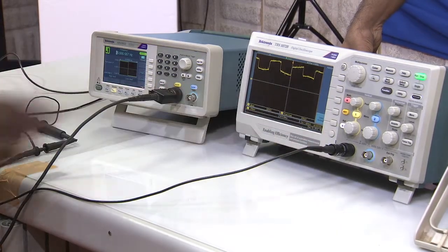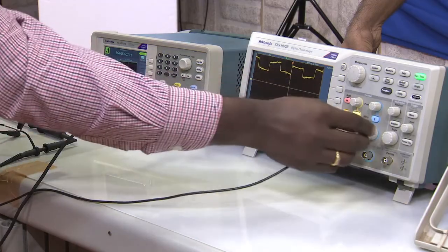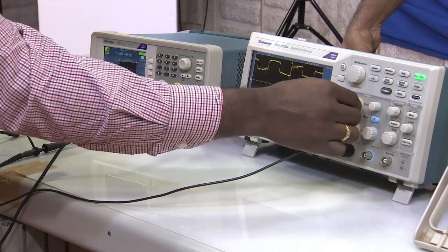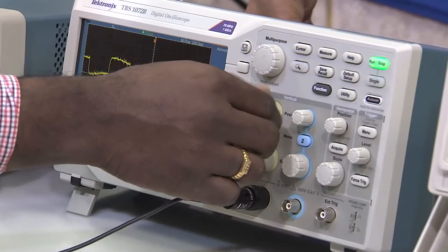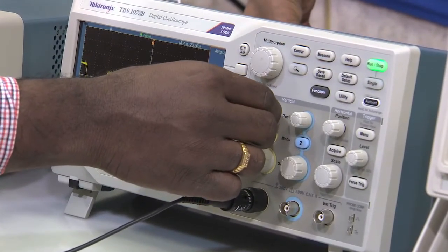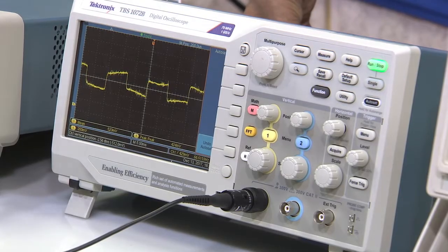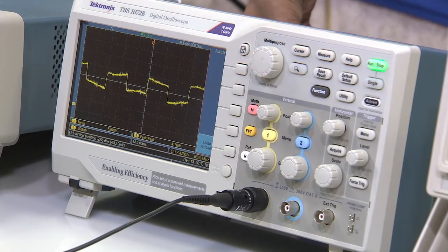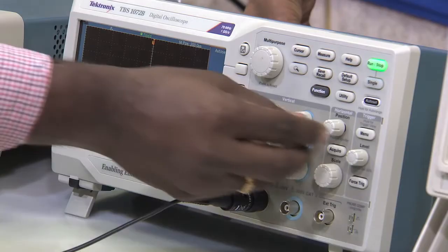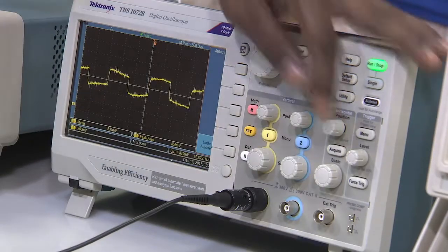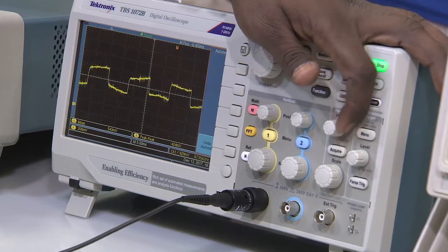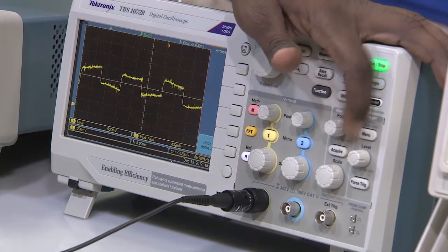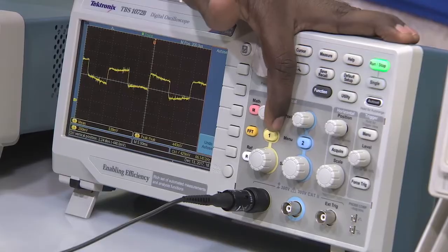Now, can you please move it down. So, there is a function for positioning, right, one is vertical positioning, one is horizontal positioning. By vertical positioning he is moving the vertical position. So, you can see vertical, horizontal. Can you please show it? You can always see, but see this is horizontal. When you move the horizontal, the waveform will move along the horizontal axis. When you move the vertical, it moves along the vertical axis.